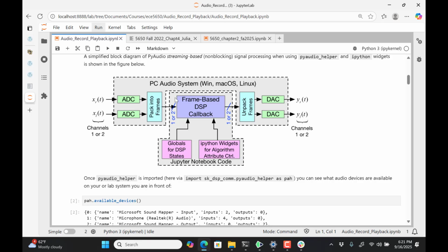The longer you make the frame, if I was teaching real-time DSP, I'd be talking about this a lot, but the longer you make the frame, the easier it is for the PC to manage to fit in time to do its job of processing that frame, because our operating systems are responding to mouse events quickly. They're multitasking all kinds of other things. So a long frame makes it easier to keep the frame contiguous and not have glitches and things.